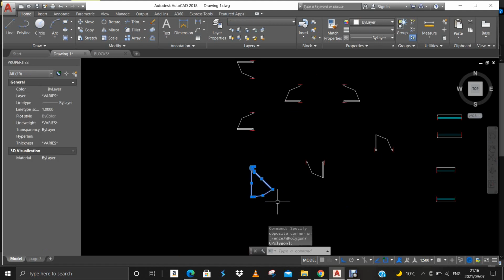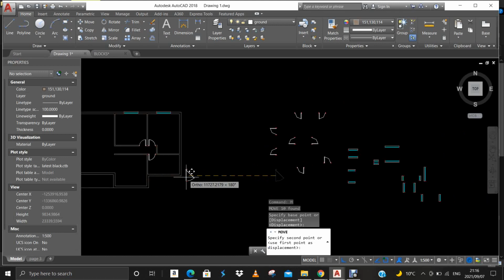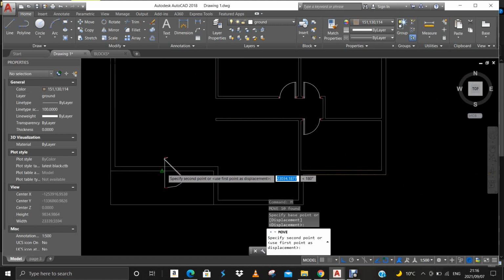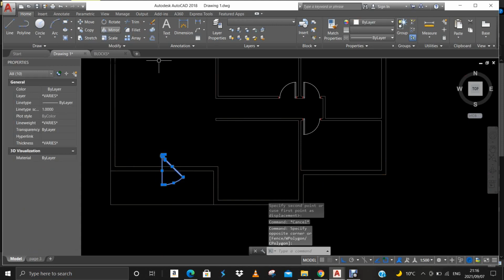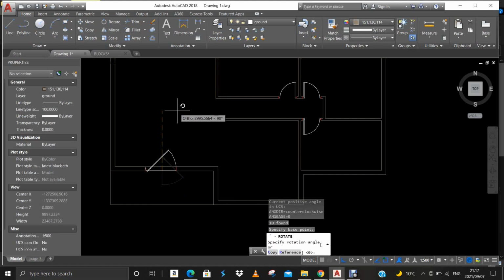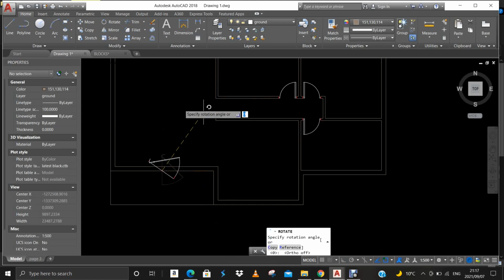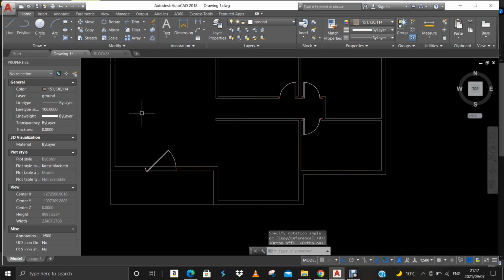I'm gonna select that door and bring it here, which is a pivot door. I'm gonna place it right on the center. Select the door again, and there's the rotate command. But I'm gonna type RO for rotate and spacebar and select the center point. And with my ortho on, see, with my ortho off, that's what it does. But I want it on because I want the door to be 90 degrees like that.